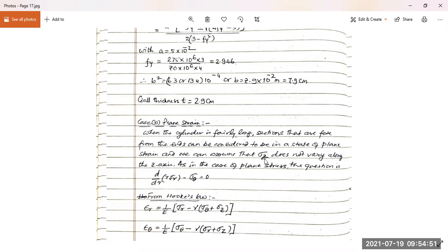Means we are using r, theta, z as our coordinate axes in this case of axisymmetric stresses, where r is the distance of the point of our consideration from the origin O. Theta is the angle that OR makes with the x-axis, in the anticlockwise direction, and z is the axis mutually perpendicular both to r as well as to theta, or both to x and y.